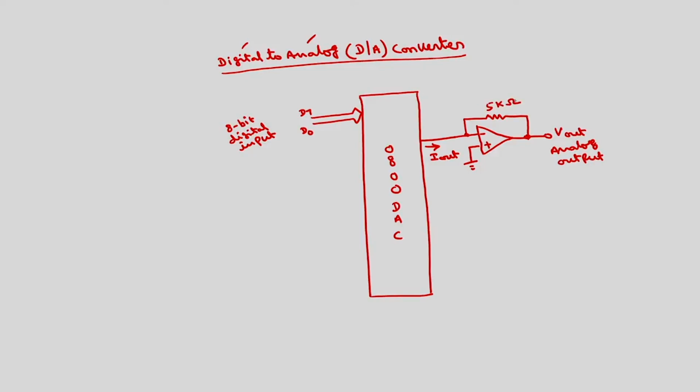And there are several pins, like there will be two reference voltages. If I want to use only one single polarity reference voltage, the other polarity has to be grounded. You have to connect through some resistance. Depending upon this resistance, the I reference current will change. So this pin is V reference minus. We are grounding it.